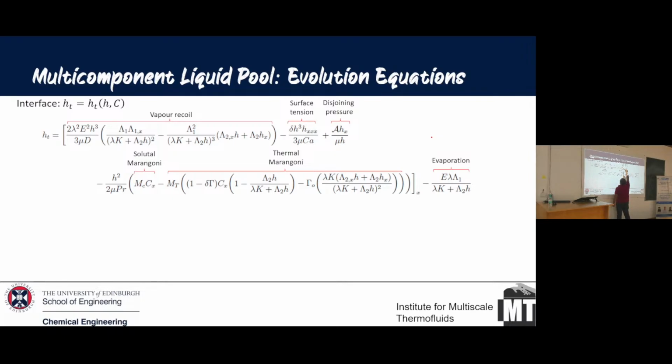Of course, one of the things is surface tension, which plays a crucial role. And there is another term which I have put here, the disjoining pressure, and there is a reason for that. Whenever you have a very thin film, I've just exaggerated this, the height of the interface looks like that. It is forming these waves, and sometimes the height of the interface goes very close to the wall.